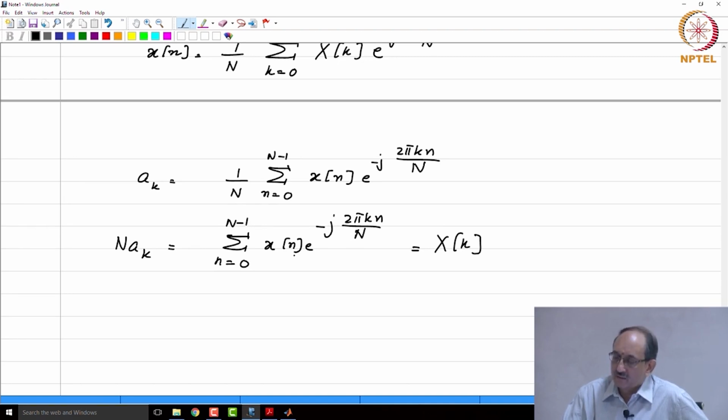Basically these things give you a conceptual framework in which you can bring in ideal signals and not worry about the approximation that you are making. Just like an impulse is a very good approximation for a short duration pulse. All transients would have died down when you turn on the function generator and apply it to a circuit. Quickly the transients will die down, and then you will observe the steady state response, and that circuit is best analyzed using steady state theory, thinking of infinite duration sinusoids that were switched on infinitely long ago. So, these are models that are used in practice to approximate actual workings.